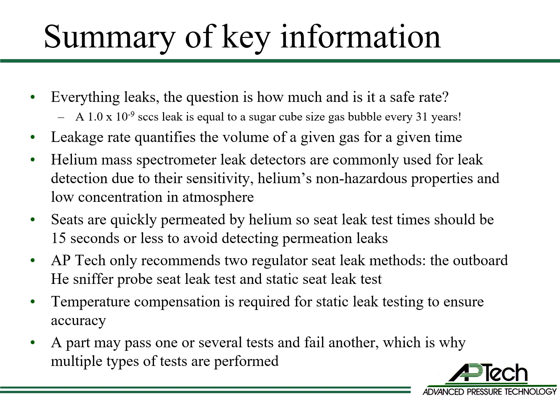APTech only recommends two types of regulator seat leak tests: the outboard helium sniffer probe seat leak test and the static seat leak test. Temperature compensation is required for static leak testing to ensure accuracy. A part may pass one or several tests and fail another, which is why multiple types of tests are performed.